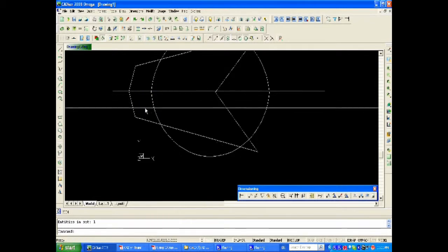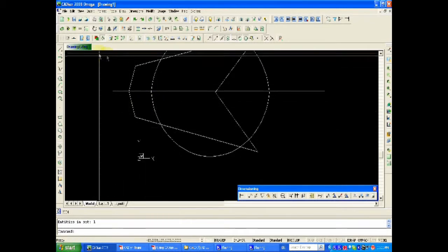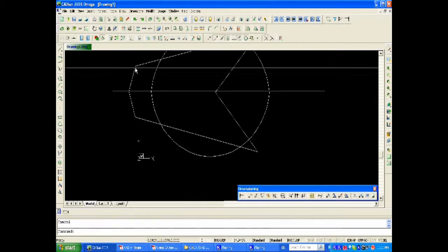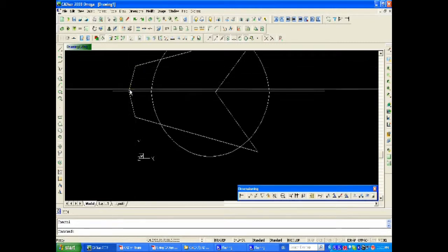The other function we have here is called the scale command, and you have the stretch command. Stretch commands you're going to use a lot. Okay, I want to stretch these two lines or those entities from this point to that point. So how do we do that? This point must end up right over there. So we use a stretch command here, and from the right to the left, click across the components.